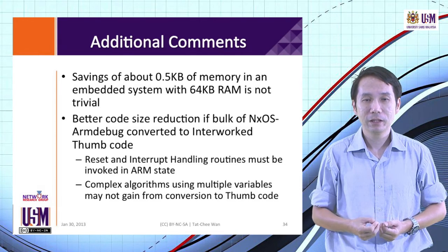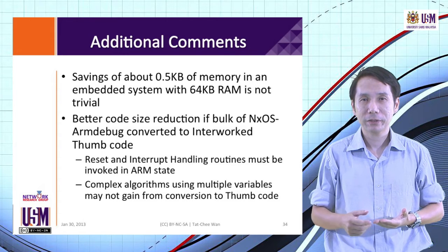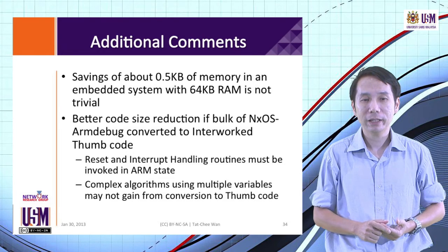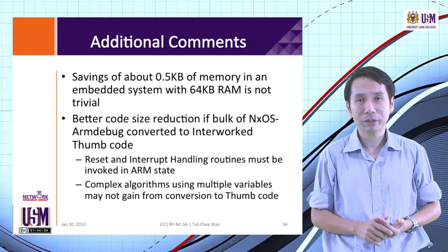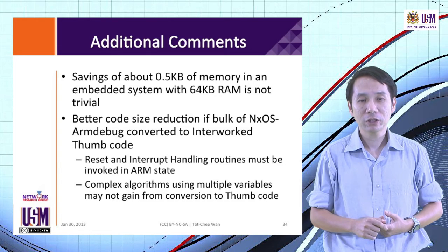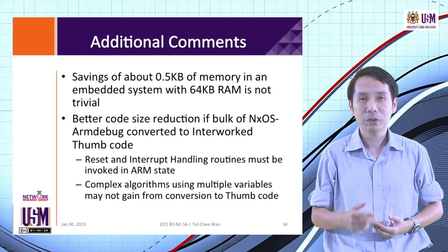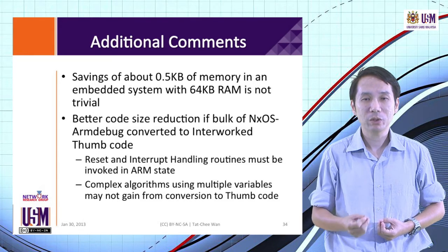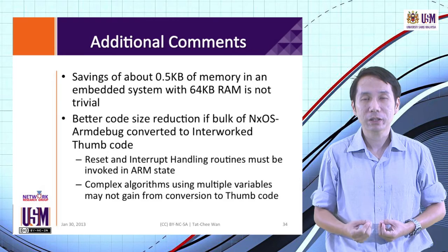Here, let's look more carefully in the object file generated for the Tribot application, which have been written directly by us. First, we look at the various files. There have been modules that have been generated, which is division.o, helper routines.o, PID.o, and Tribot ARM or Tribot thumb.o. Division.o and PID.o are both ARM-only routines. So there is no code size reduction between the ARM code version and the interworked thumb code version.